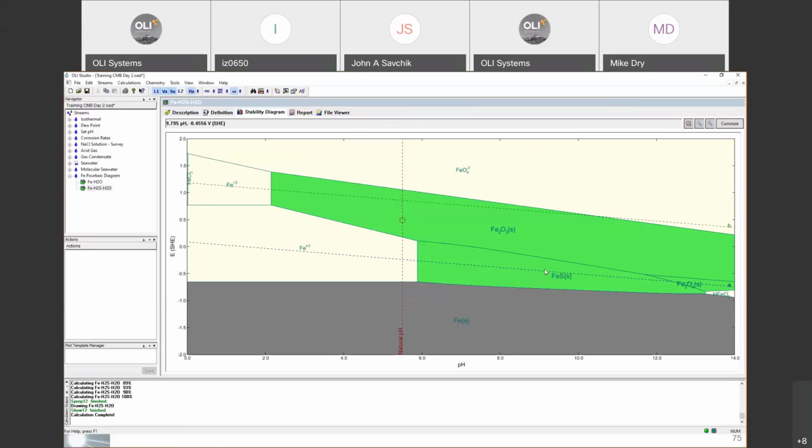Okay, so it's now being formed in a wider region of pH. Remember that before we only had this magnetite phase here, and now by adding the H2S to the system, we instead form the iron sulfide. The magnetite phase reduces, is less favorable in these conditions, and iron sulfide is being formed at a wider region of pH. So you'll see that at around pH 6, this iron sulfide layer is being formed and is going to act as a protective layer on the surface of the iron.